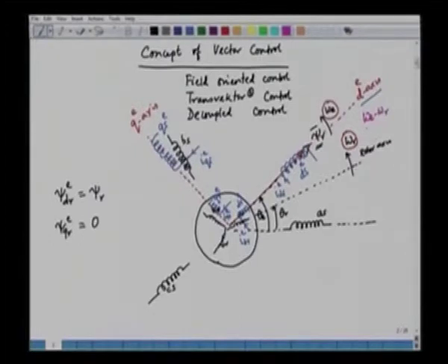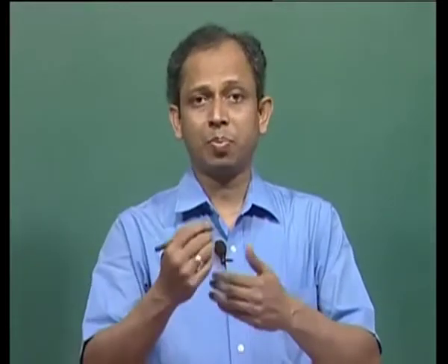That is written as omega_sl, and omega_sl is called the slip speed. When we are writing down the equation of the rotor, the physical rotor is moving at a speed of omega_r, but the hypothetical winding in the rotating reference frame is moving at a speed of omega_e. The relative velocity between these two is omega_e minus omega_r, and that is the speed at which the rotationally induced EMF will appear in the rotor equations.